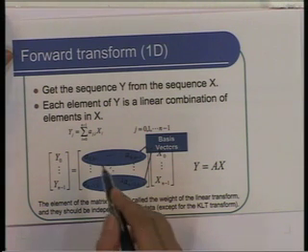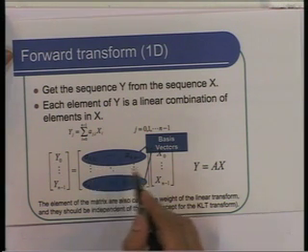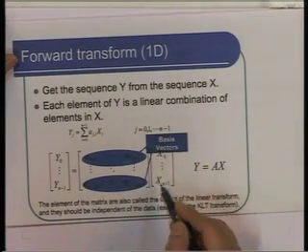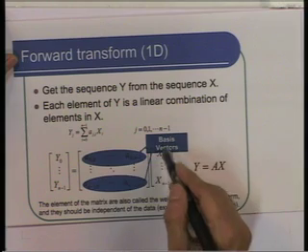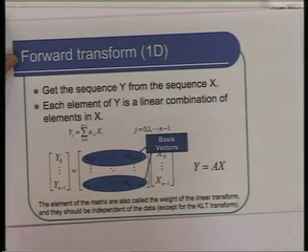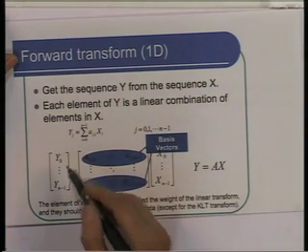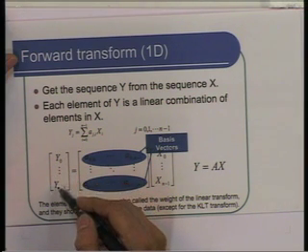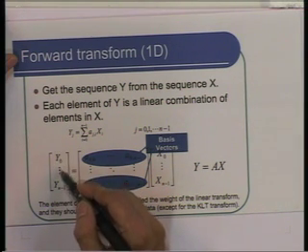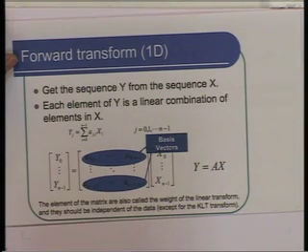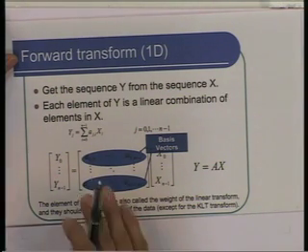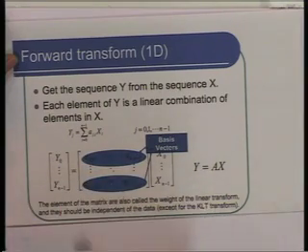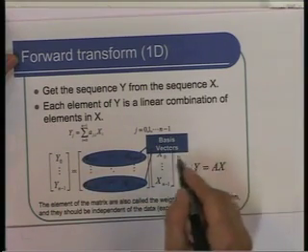Now, what these basis vectors do in fact is pick up the low and high frequency components of this data, and normally the coefficients decrease in the order of y0, y1 up to yn minus 1, and because of this y is now more amenable to compression than x.